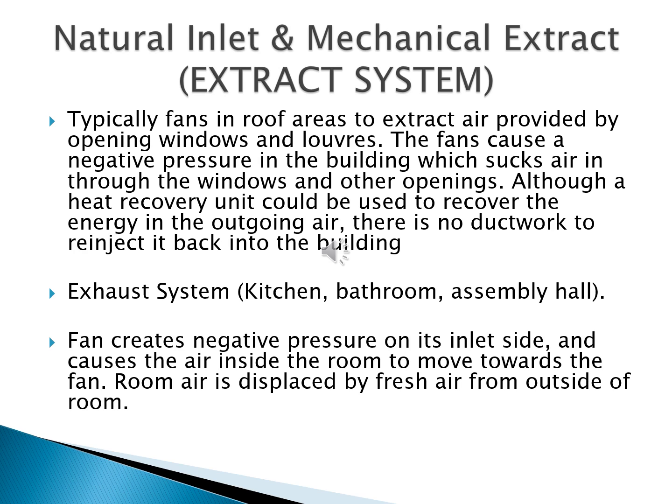Natural inlet and mechanical extract, or extract system, is typically fans in roof areas to extract air provided by opening windows and louvers. The fan causes a negative pressure in the building which sucks air in through the windows and other openings. Although a heat recovery unit could be used to recover the energy in the outgoing air, there is no ductwork to re-inject it back into the building.